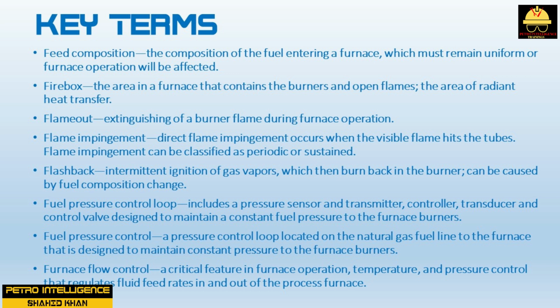Flameout is extinguishing of a burner flame during furnace operation. Flame impingement is direct flame impingement occurs when the visible flame hits the tubes. Flame impingement can be classified as periodic or sustained. Flashback is intermittent ignition of gas vapors, which then burn back in the burner, can be caused by fuel composition change.